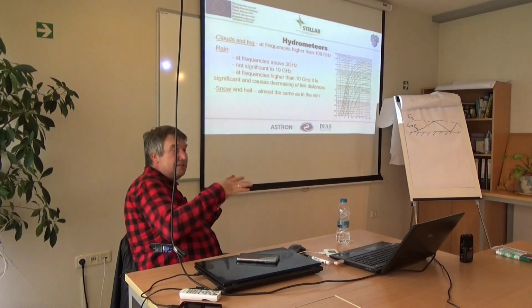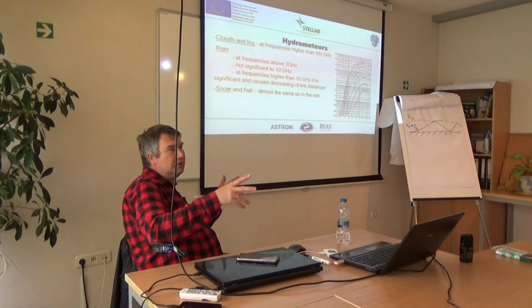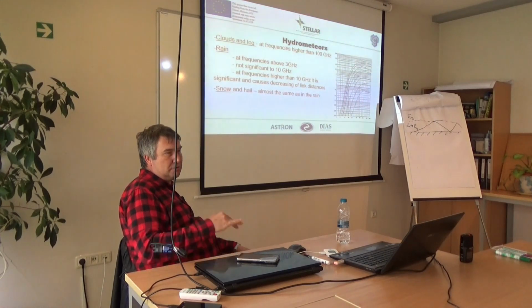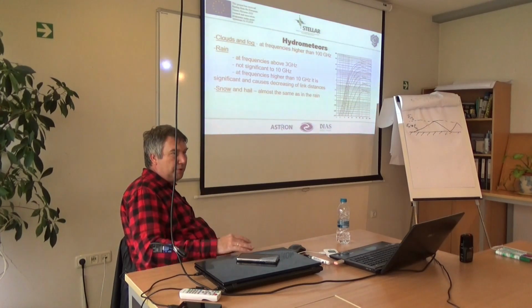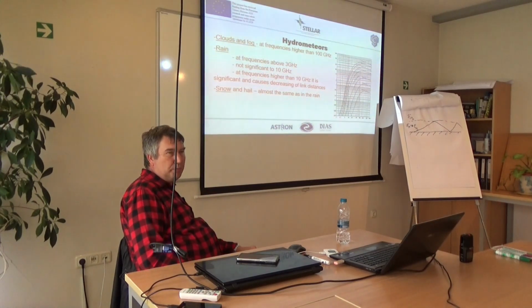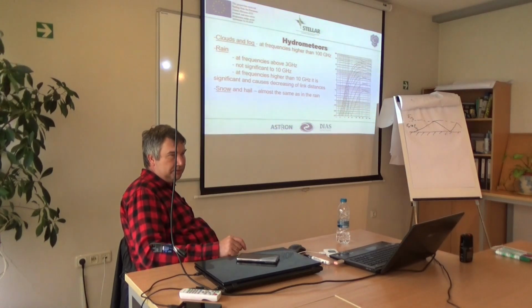If in the first case it is 60 kilometers, in the second case it could be max 40 kilometers. Because if we have heavy rain, the attenuation will be very high, and the link will be interrupted.